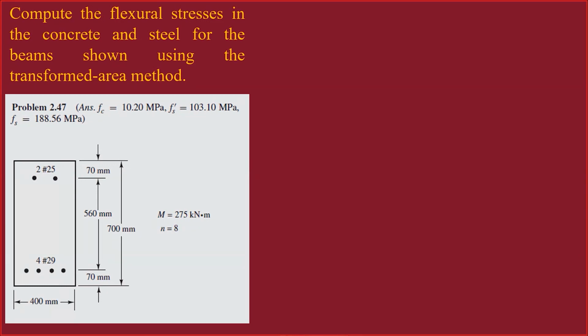Compute the flexural stress. To do this, the first thing we do is to locate the neutral axis, as we did in the earlier assignments. You have to get the distance of the neutral axis from the bottom fiber or from the uppermost fiber. The most important thing is that you can locate the neutral axis. So how do we locate the neutral axis?